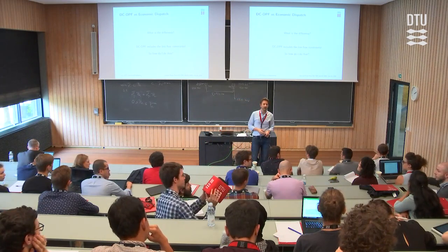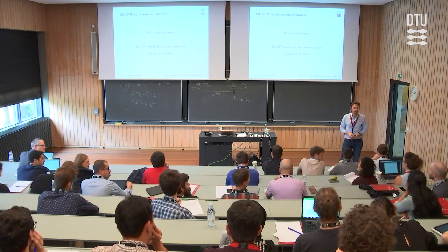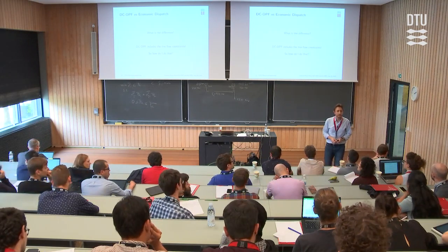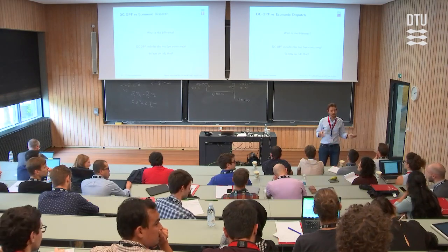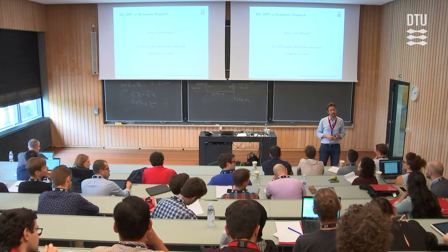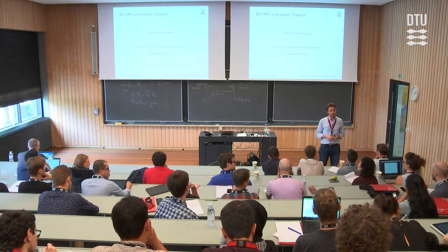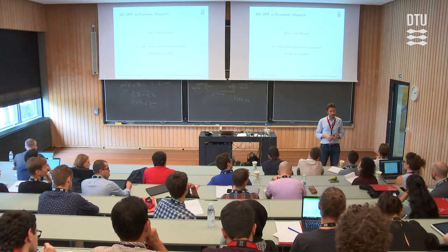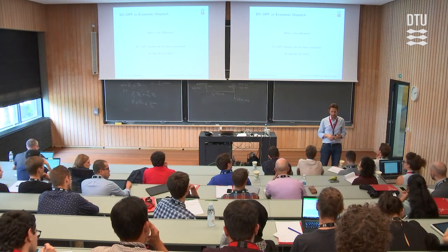Yeah, David. I just have a question before we move to DC-OPF. Okay, so you said that the economic dispatch is basically used to clear markets, right? It's used to clear power exchanges. Yeah, types of markets. But since it doesn't represent reality, you have no congestion possibilities. If you add those line constraints, then you will have different prices. So basically the marginal system cost as provided by the economic dispatch is not the actual cost of the system. So what's the rationale behind still using economic dispatch?